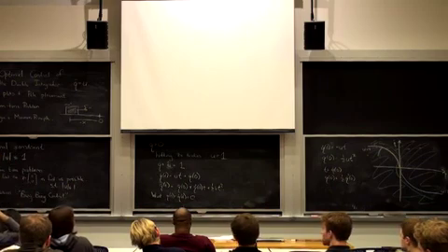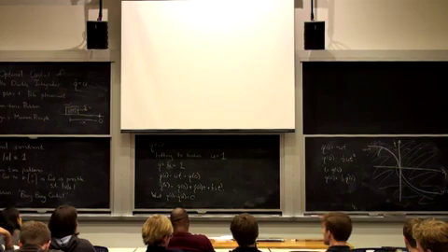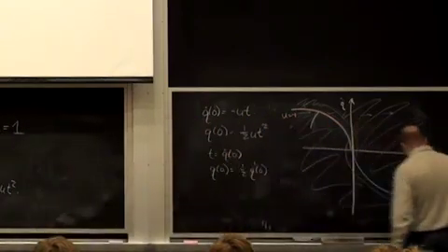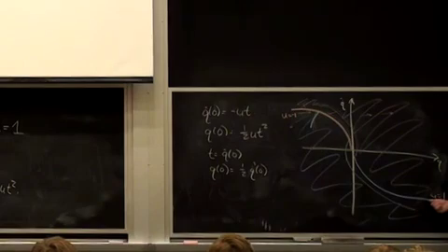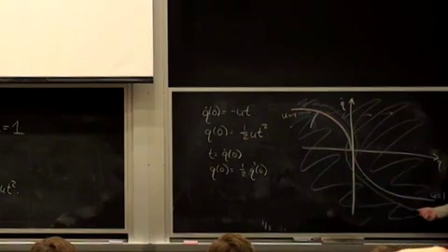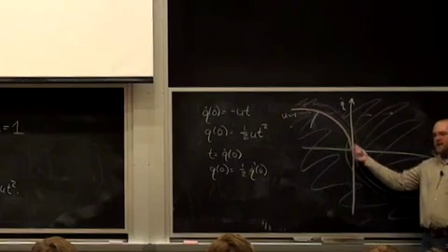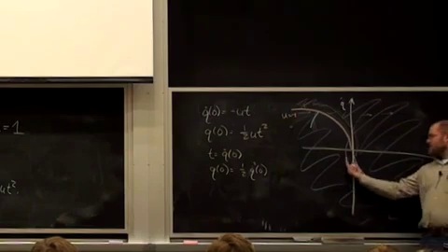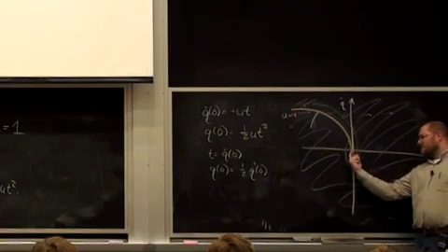Bottom right, below the line. Mm-hmm. Why do we overshoot? So tell me where, bottom right? Okay, so here, this is the place where if I decelerate, I get to the origin, right? If I'm here, then I have a little bit more velocity in the same position, right? So if I hit the brakes, I'm not going to stop in time, right? So I don't quite decelerate fast enough to get here because there's limited torque. So I just slip past it until my chance to come in the other way again.